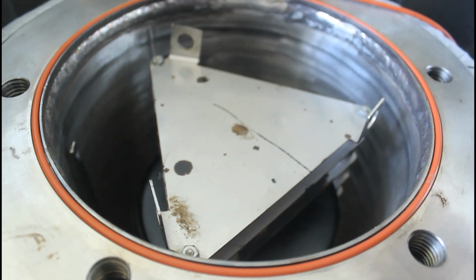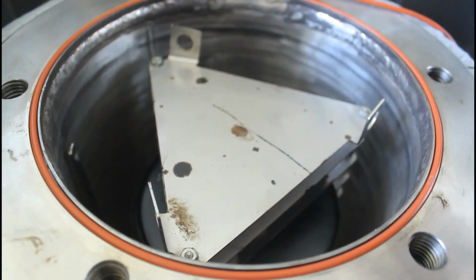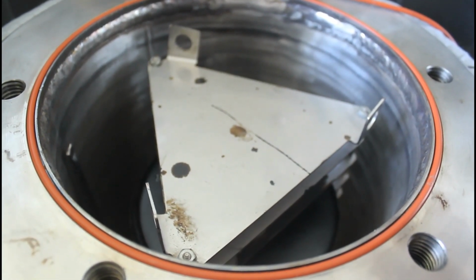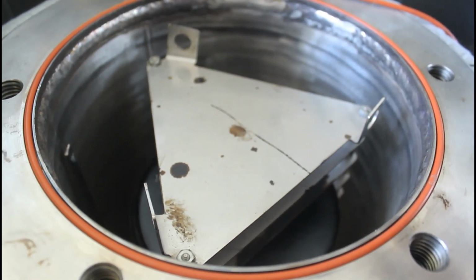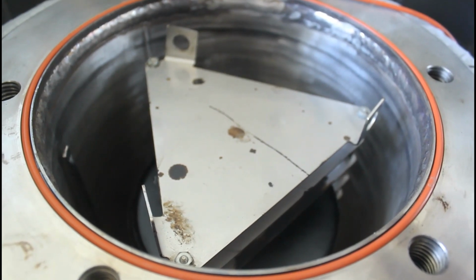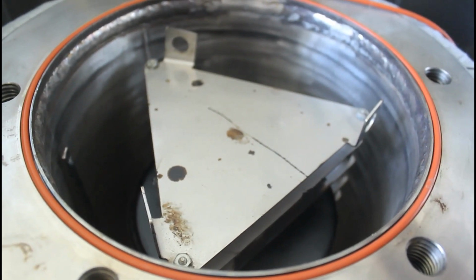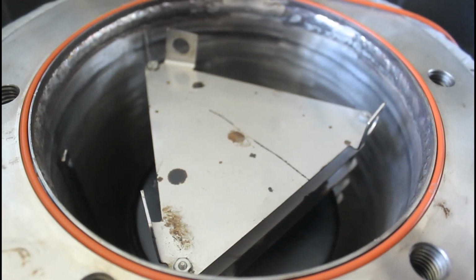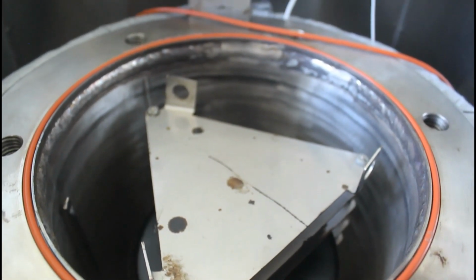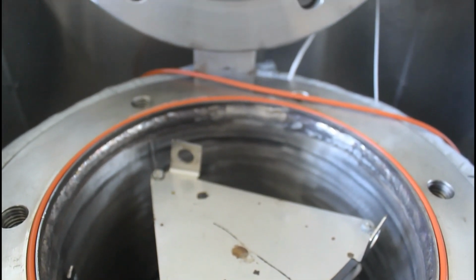In this condition it undergoes accelerated oxidative aging, where it loses a lot of components. It will undergo both physical and chemical changes. Once you get the PAV bitumen, you can study what changes have happened after PAV aging, physically and chemically. Basically we are trying to simulate long-term aging.